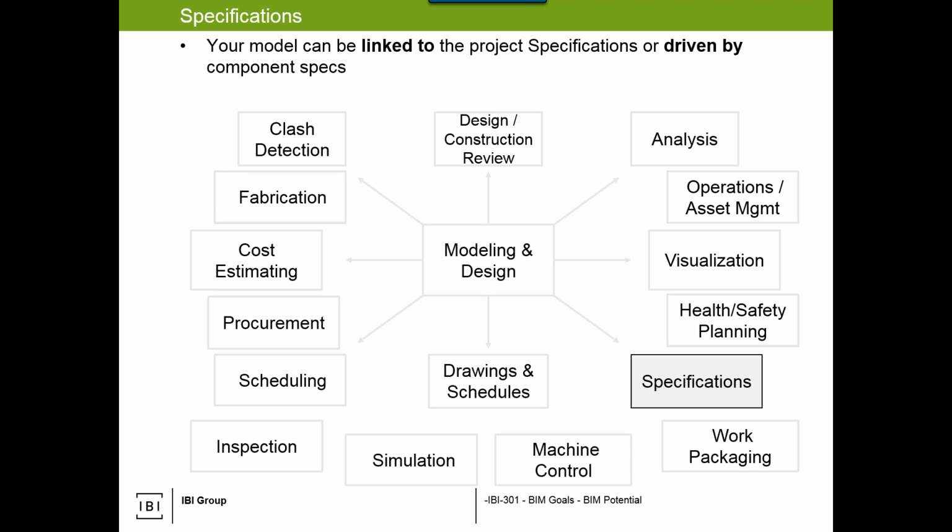From the other perspective, if we're on industrial projects, we could use specification information to drive our model. I have experience with plant piping, and that's where that came into play, where the piping specs would drive how I model and what I can model. A very simplistic example is if I'm using copper piping, the spec will prevent me from having a 2-meter diameter copper pipe because that cannot be made, it cannot be procured, it just does not exist.